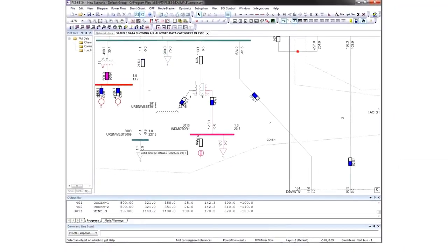Fundamentally, a solution for a power flow case is the set of voltage magnitudes and angles at every bus in the case. From this vector, you can derive flows, currents, megavar inputs from generators, and any other quantity used to monitor the state of the system. Based on the settings of the diagram, flows are noted numerically at the terminals of the buses.